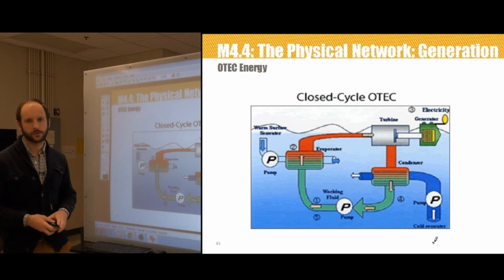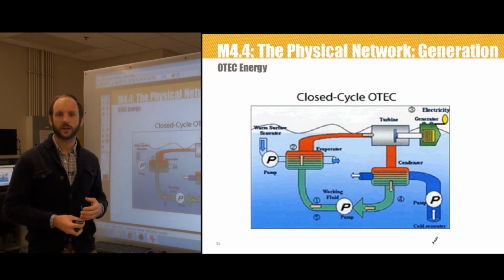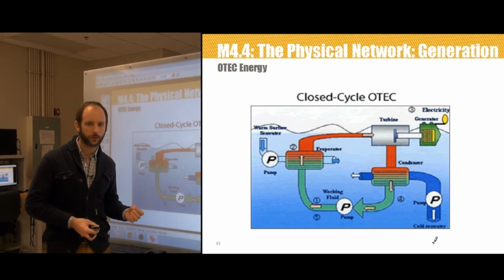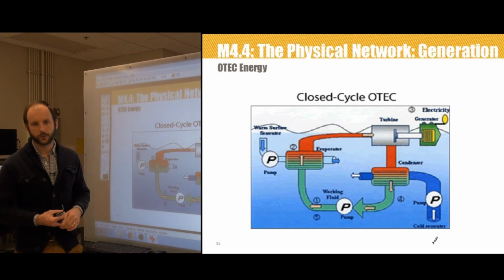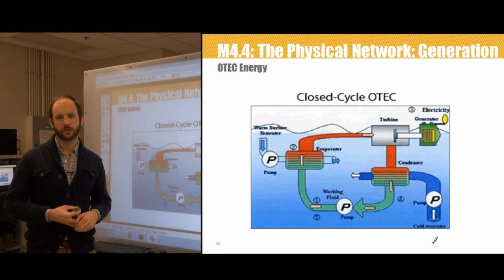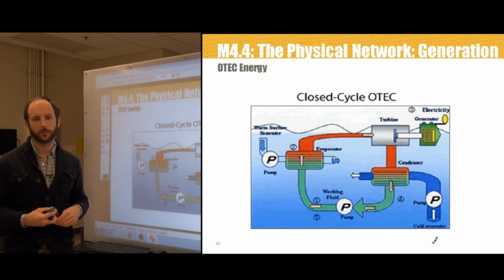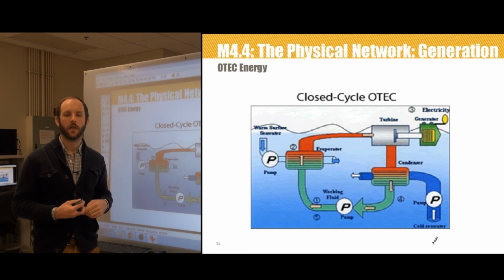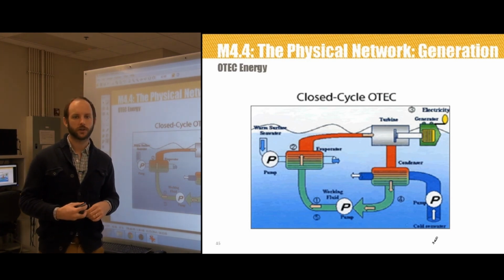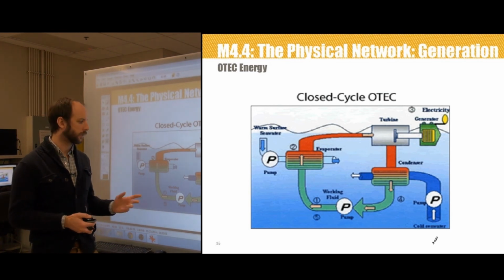Finally, the last technology for ocean is ocean thermal systems, and these conversion technologies create electricity via either open or closed loop thermal systems. In a closed cycle system, warm surface seawater is pumped through a heat exchanger, which is used to vaporize an extremely low boiling point fluid, such as ammonia. That vaporized fluid then turns a generator. Cold deep seawater is pumped through a second exchanger, which condenses the vapor back into a liquid and then allows that cycle to continue.